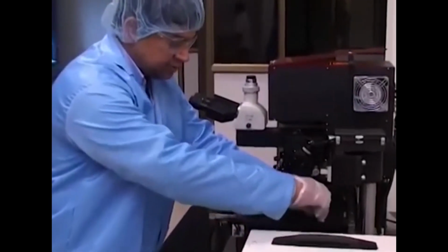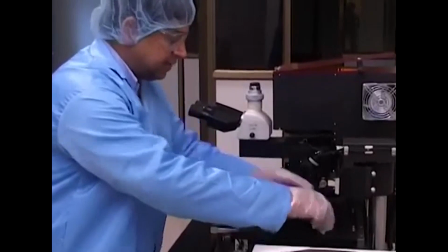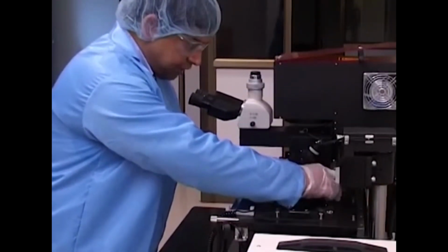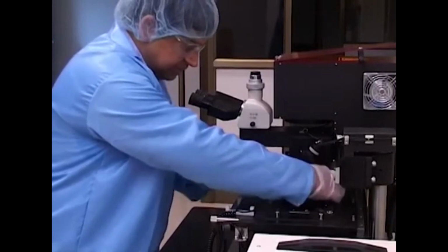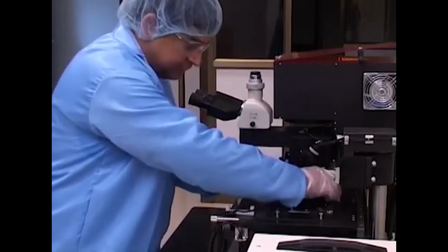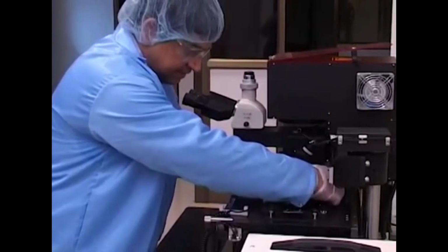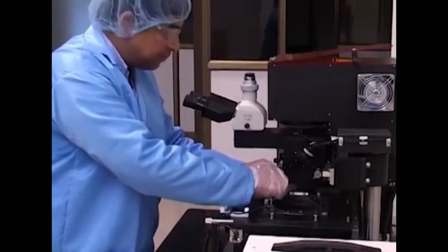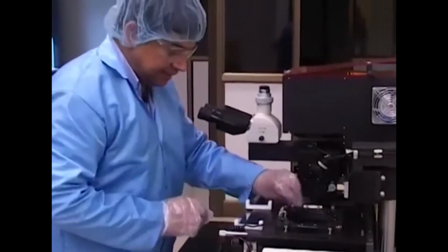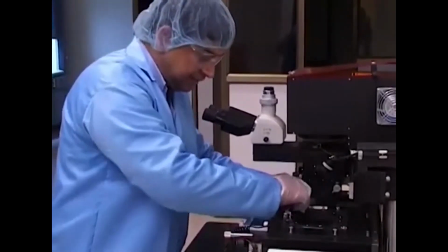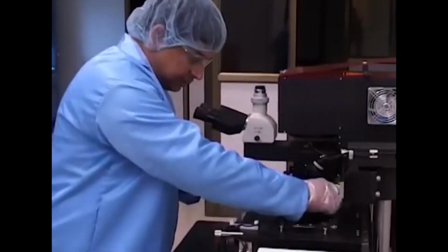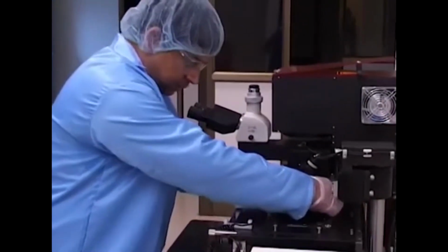Okay, so we are going to just ensure proper gripping of the mask holder onto the surface of the stage. The stage is, by the by, going to move along with this whole mask holder to the exposure zone, which is underneath the scope, as I will be showing you in a little bit, and it has to have a tight grip for the purpose of proper alignment with the wafer on the surface.